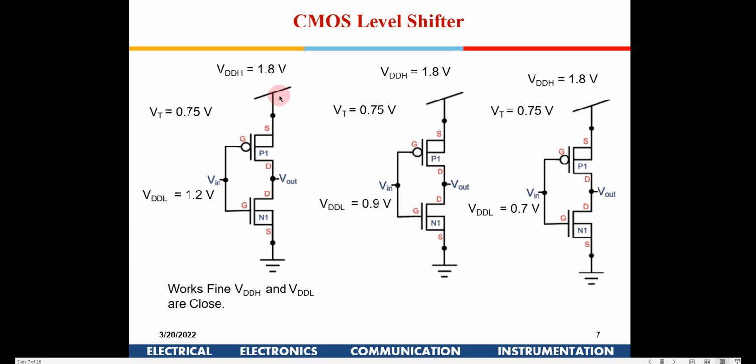We learned that the total power consumed by a circuit is a strong function of VDD. So in all those non-critical paths, you can scale down the voltage. Once it is scaled down, the output voltages also will be less, and finally when we have to merge those signals, we will have to again bring back the signals to the required level. So for all those applications we have a circuit which is known as a level shifter. Can we use just a simple inverter to shift the level? Let's see what the problems are.